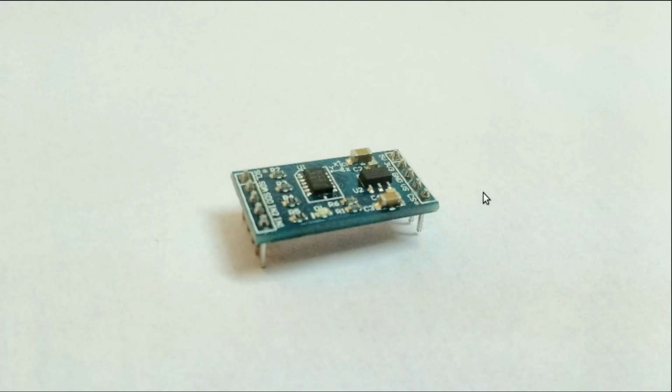Next we'll need one accelerometer, and I'm using the ADXL345 accelerometer, and this is its breakout board. As you can see, X is in this direction, and Y and Z are in the other directions. This is a 3-axis accelerometer with an I2C interface. If you can see, the SCL and SDA pins are there. So we'll be using this ADXL345 accelerometer. And don't worry, I have mentioned a link to a written write-up of this whole project, so you can even go through that.